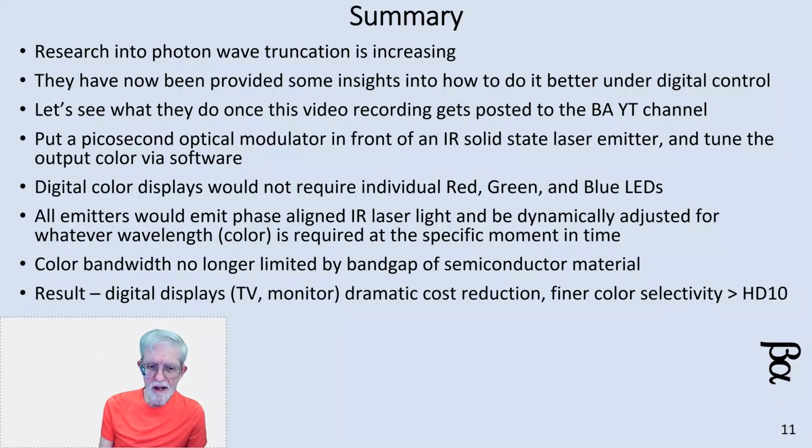So if you can do that on a per emitter basis in a display, you no longer have to make different chemistries of LEDs, basically associated with what is known as the band gap of the semiconductor material, to get your red, green, and blue. You can dial up whatever color you want based upon what wavelength you want.